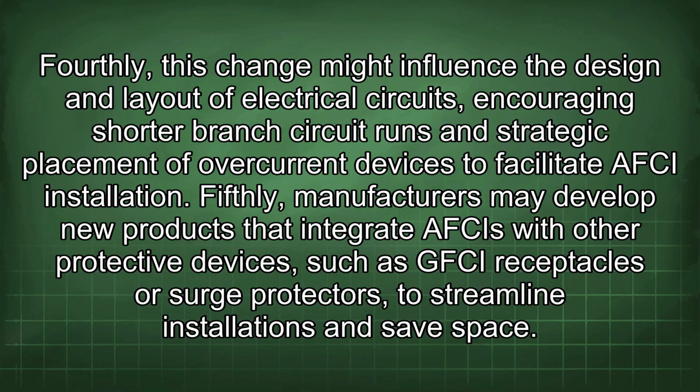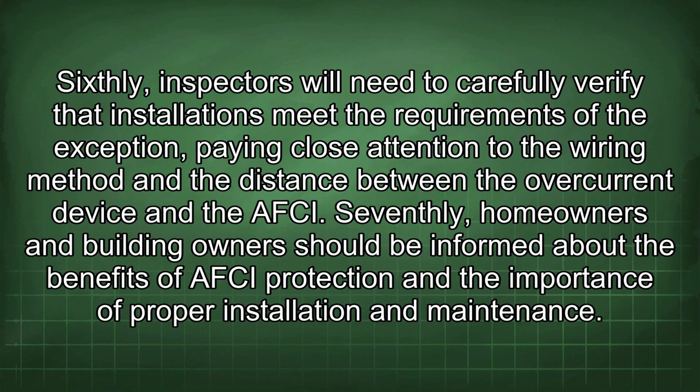Fifthly, manufacturers may develop new products that integrate AFCIs with other protective devices such as AFCI receptacles or surge protectors to streamline installations and save space. Sixthly, inspectors will need to carefully verify that installations meet the requirements of the exception, paying close attention to the wiring method and the distance between the overcurrent device and the AFCI.